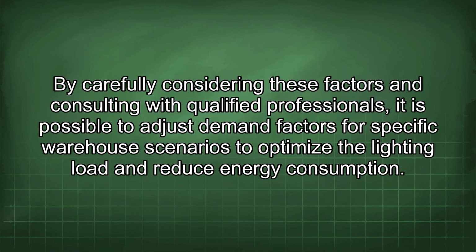By carefully considering these factors and consulting with qualified professionals, it is possible to adjust demand factors for specific warehouse scenarios to optimize the lighting load and reduce energy consumption.